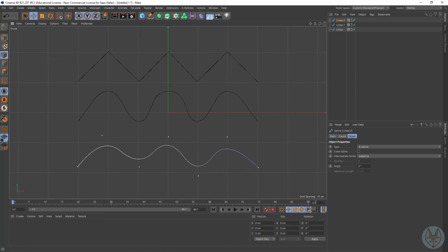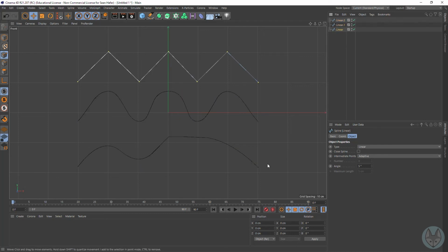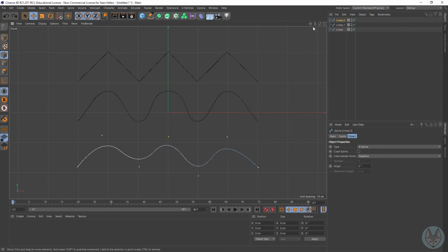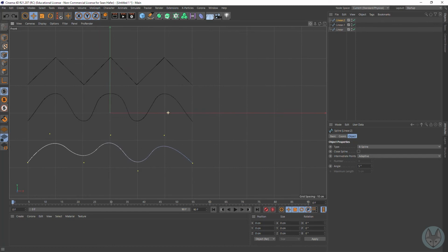So if we come down here, we can start creating some really smooth curves, right? These are great for camera paths because it's hard to get a kink in them, like a really rough sort of corner point almost. And speaking of corner points, if you want a corner, you almost have to put two of these on top of each other to start to get that idea of a straight corner. So that is where that will come in handy here in a minute when we talk about subdivision surfaces.